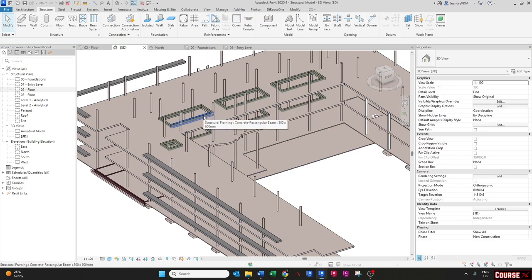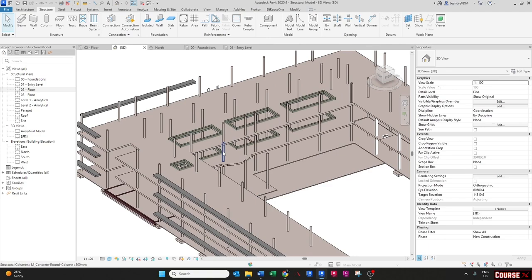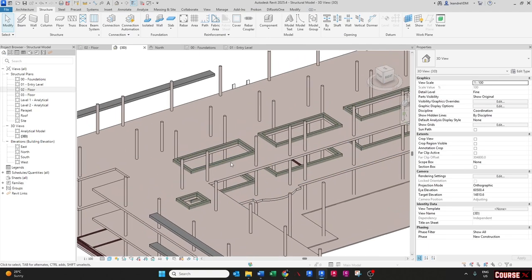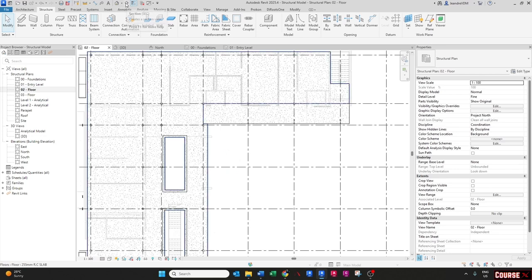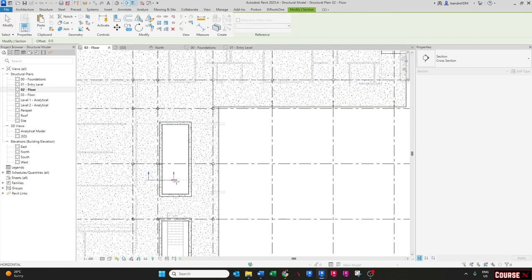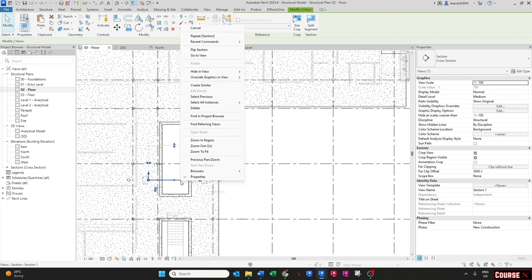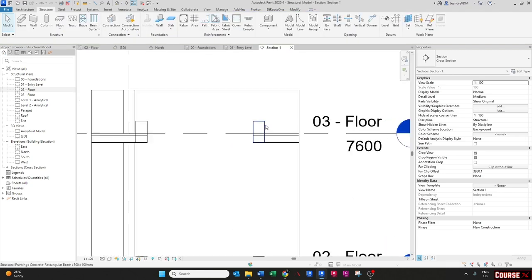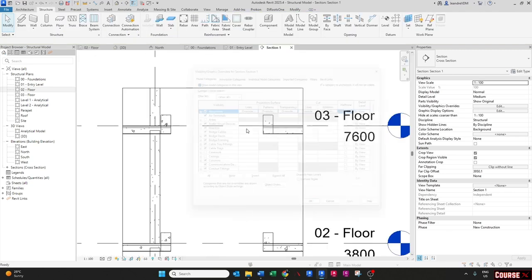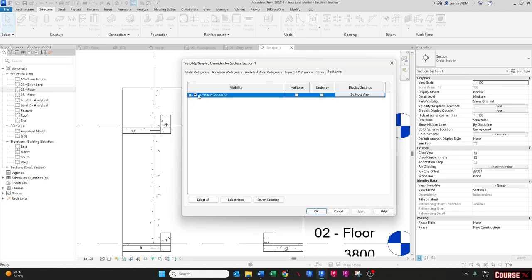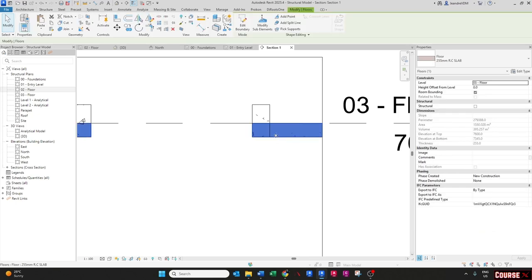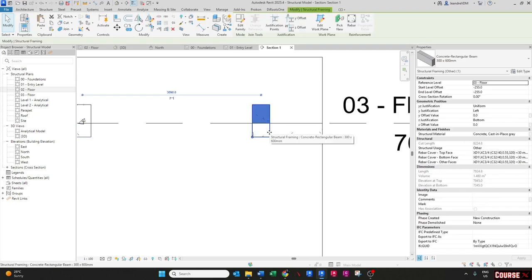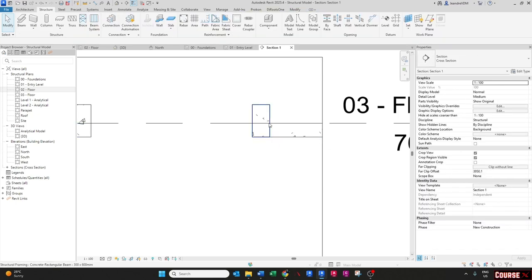You can see if I go there, let's just draw a section, and I'm going to show you why I also change it. Go to the second floor, section indicators at the top, just draw a section like that. I go to the view. Now I'm just going to say VV on my keyboard, Revit links and architect link, and just turn that off. So now you can see you don't have a very nice join feature. It doesn't join there because it's not the same material.